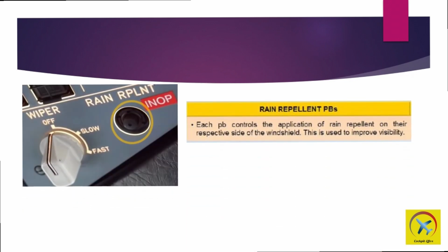Rain repellent fluid has been phased out as part of the worldwide effort to protect the ozone layer. Airbus industry has been actively working on alternative solutions and is now in a position to provide the operators with a choice of environmentally friendly rain repellent fluid or windshield hydrophobic coating.